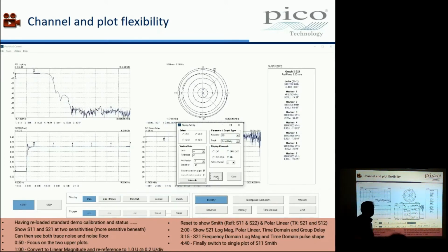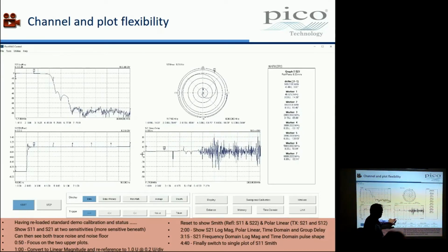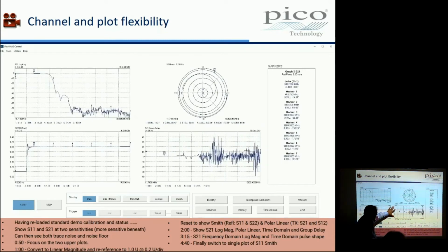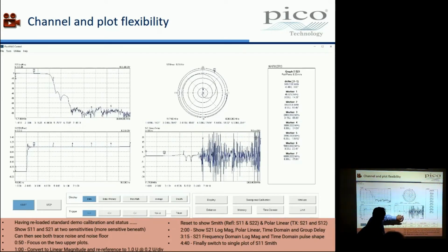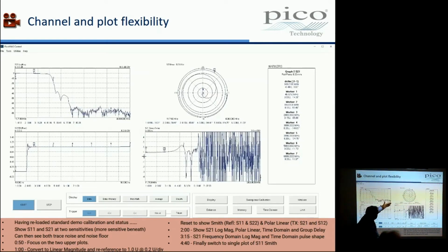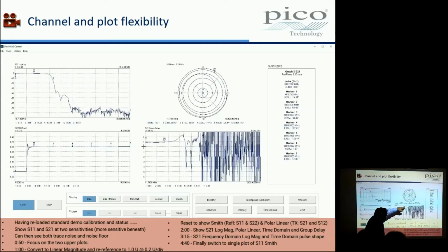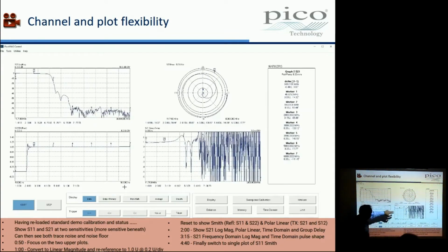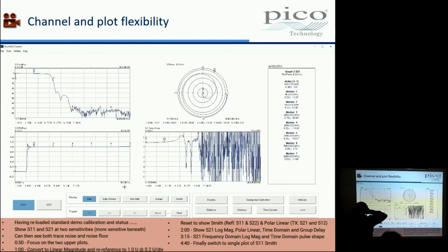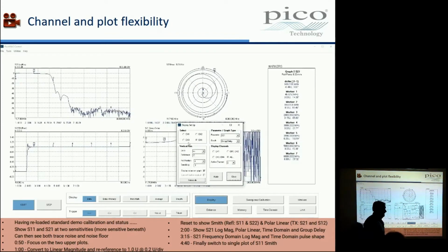Channel 4 S21 group delay. Here we go. So now what's happened here is I've still got frequency along here, but this is a time axis now. Just going to pull out the sensitivity here. And what this begins to show me here is that delay, initially, can't read the numbers, delay is rising and then falling, and you can see that more or less aligns with the roll-off point of the filter. And as we said earlier, that's differentiated, or the slope of phase change with frequency.